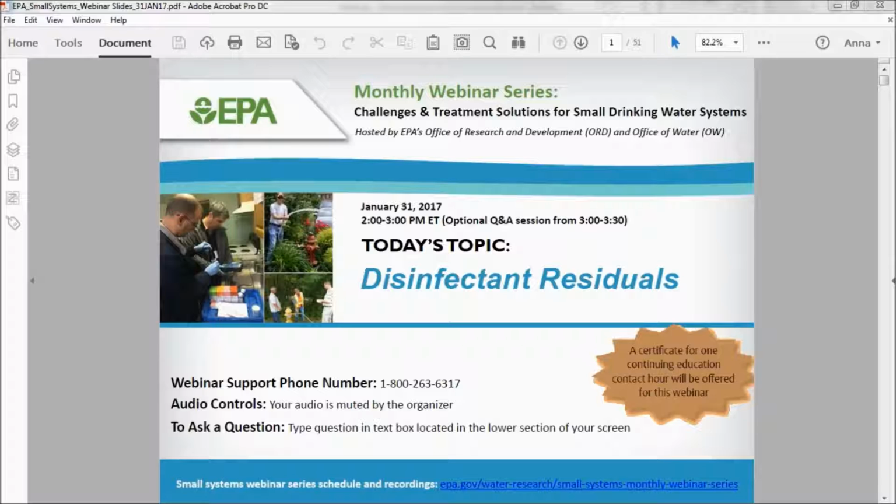Okay, and maybe I'll throw this out to both, but it was mentioned about overflushing. Can you expand on that comment? Well, overflushing would be getting back to one of the flushing approaches I talked about, flushing till you get a good result. If you're at a location that actually has low chlorine residual and you continue to flush, you're not collecting a sample that's really representative of what's at that actual location. And that could be the same for disinfection byproducts as well.